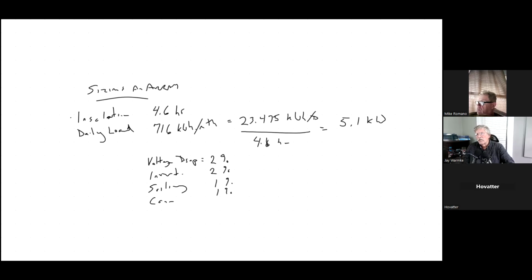And let's just say for good measure, because there are some other things like downtime, aging of the panel, inefficiencies of some other issues, I'm just going to throw in another 2% just for good measure, miscellaneous. So now I've basically said this is an 8% inefficient system, which means it's 92% efficient. So I take 5.1 divided by 0.92, and I get a 5.547.